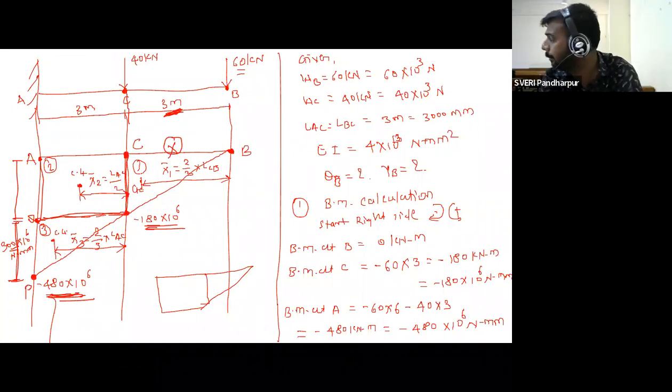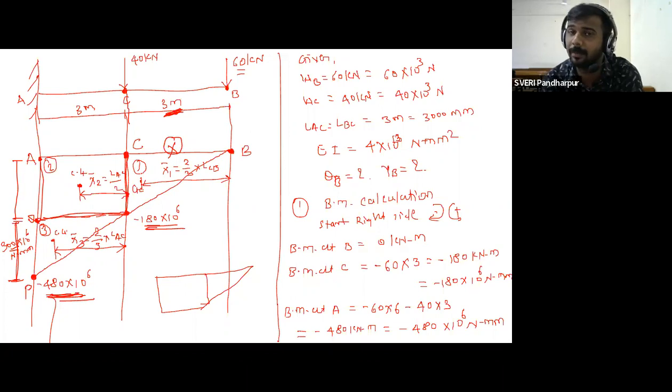So write down, for cantilever beam, while calculating slope and deflection at particular point, meaning any point, getting? Whether it is the free end or the middle, whichever it is, at particular point consider all the sections under BMD which are present at left side of that particular point,